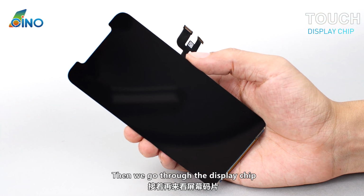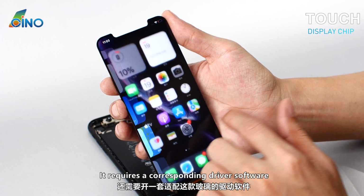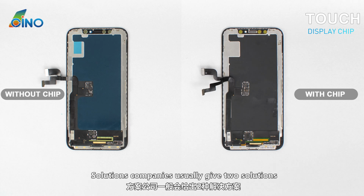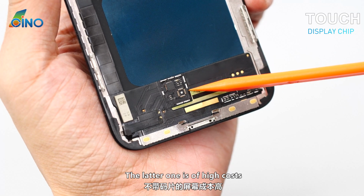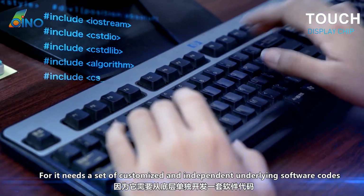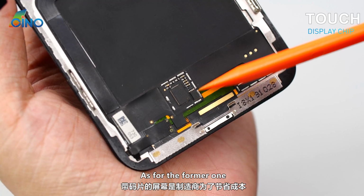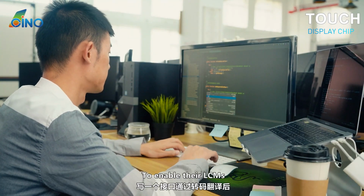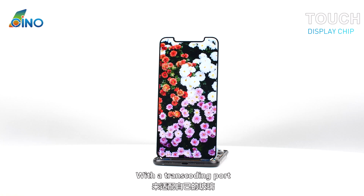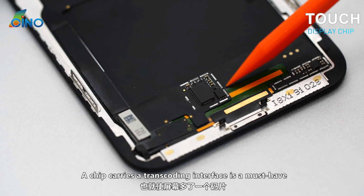Then we go through the display chip. In order to make an LCM run, it requires corresponding driver software. Solutions companies usually give two solutions: display with a chip and display without a chip. The latter is of high cost, for it needs a set of customized and independent underlying software codes to function the LCM. As for the former, the manufacturers bring some already existing codes to enable their LCMs with a transcoding port. In this way, a chip carrying a transcoding interface is a must-have.